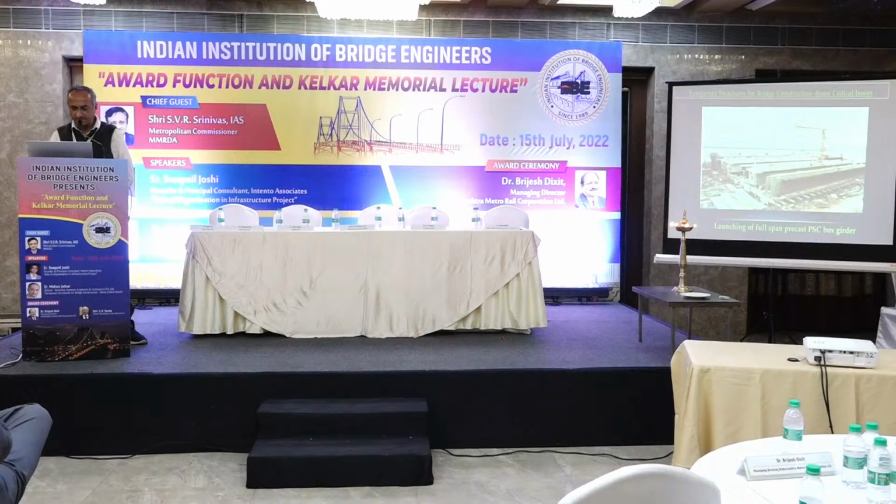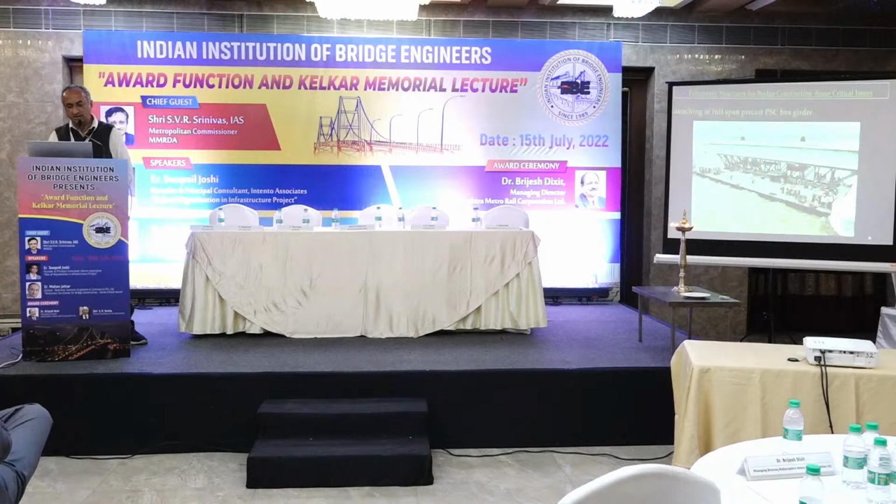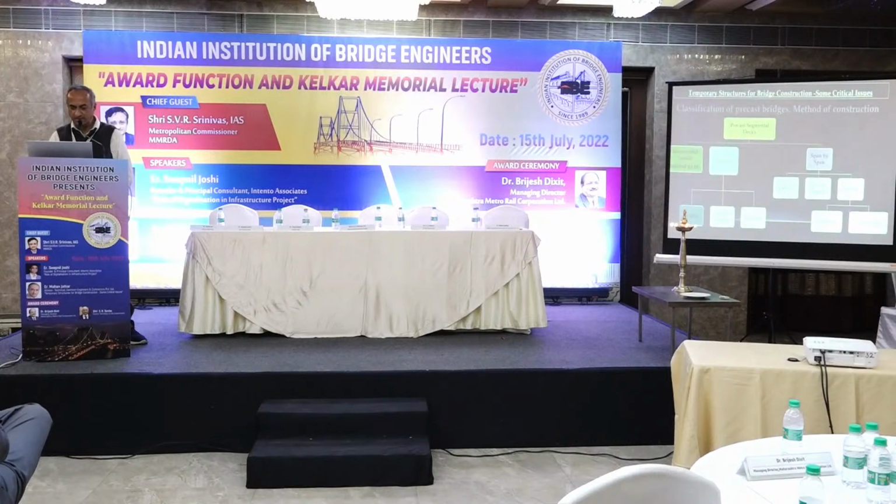Another interesting example is the Vasai Creek Bridge. The entire span, weighing about 800 tons, was cast on jetties and then taken to the location on a barge, and then using the high tide, it was lowered into position.